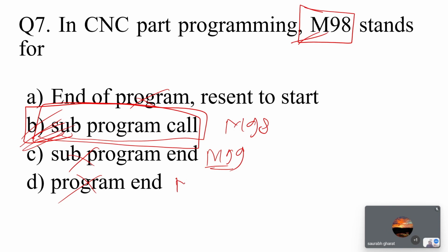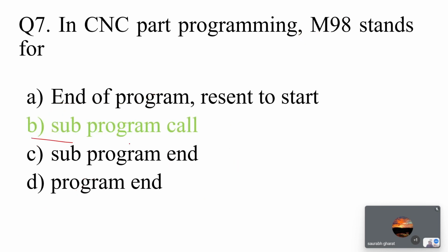I think it's M02. Go check it. So check this part, but mostly it is M02, and this is M98. Okay, so subprogram call is the correct answer.